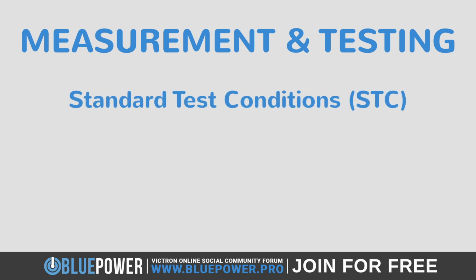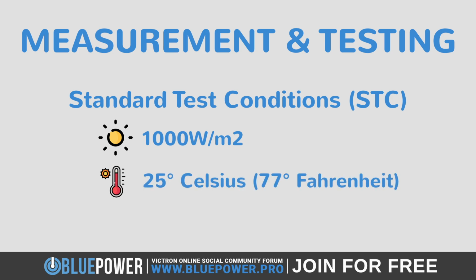The standard test conditions, or STC, are defined as an irradiance of 1,000 watts per square meter, a cell temperature of 25 degrees Celsius, and an air mass of 1.5. The STC provides a standardized basis for comparing the efficiency of different solar cells and panels, ensuring that efficiency measurements are consistent and comparable across different manufacturers and technologies.